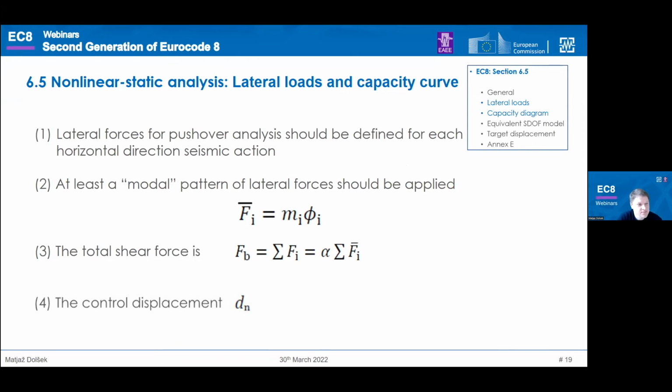So in the next part of the nonlinear static analysis, there is the definition of how the pushover analysis should be carried out. First we have to assume the lateral forces for the pushover analysis, and those are defined for each horizontal direction independently. At least a modal pattern of lateral forces should be applied.